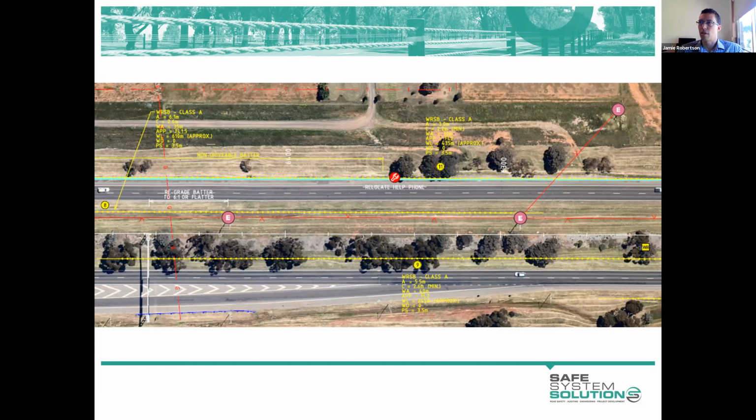And if you look closely at this drawing, you'll see some barrier offsets. A is our barrier offset of 6.1 metres, 3 metres here, that's pretty standard, 5.5 here. And if you drive along that road, you'll see barriers stepping in and out as you drive along. They're not continuous barriers, they're barriers to shield isolated hazards.